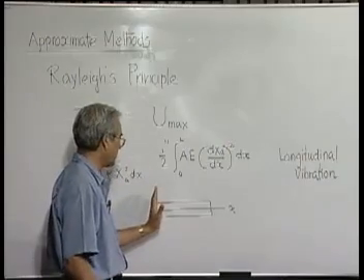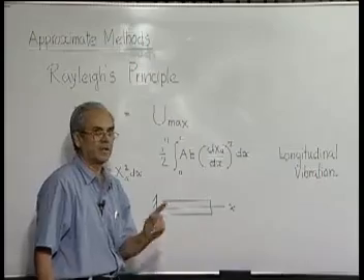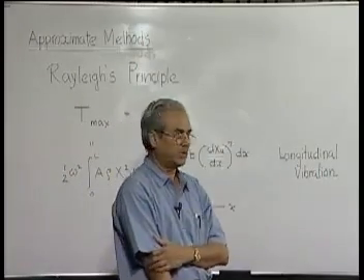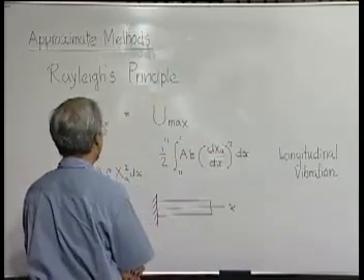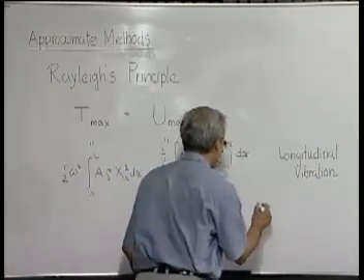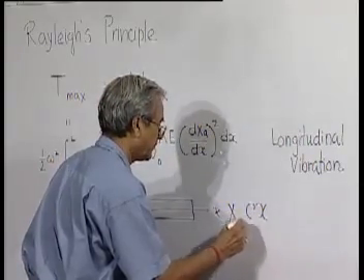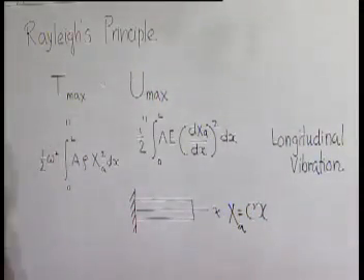So this is a geometric boundary condition, but this end is free to move, but its force is 0. That's a non-geometric or dynamic boundary condition. So at least the geometric boundary condition should be satisfied, and so we took something like this, a very simple form, and we reasonably got the answer.